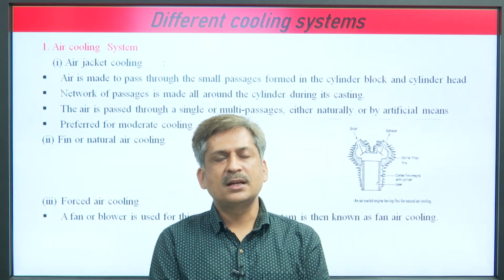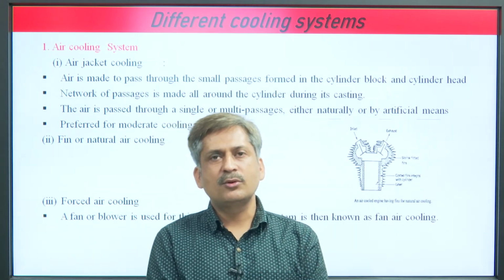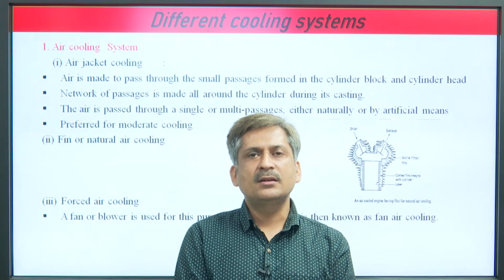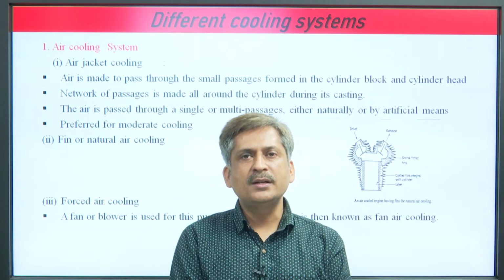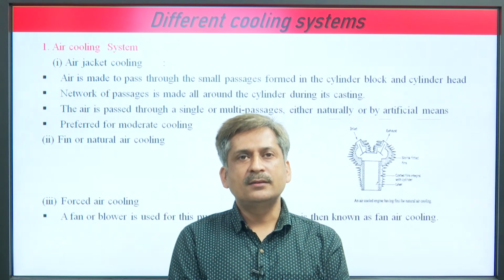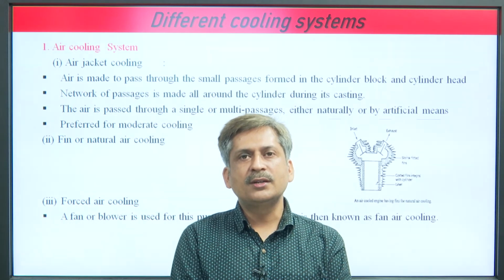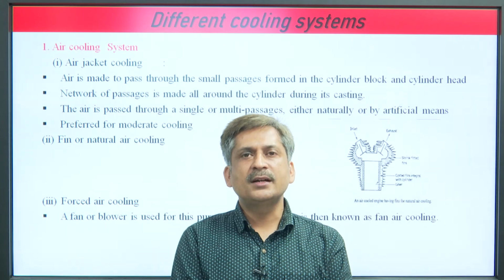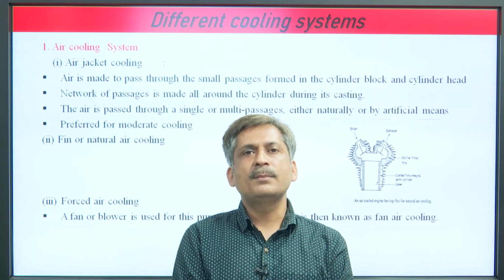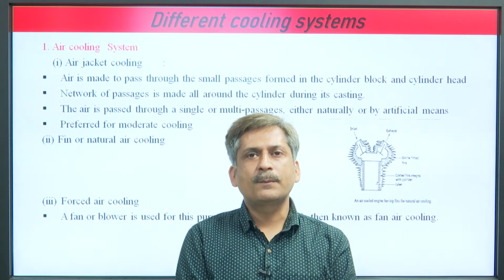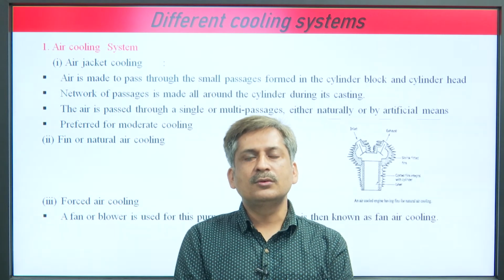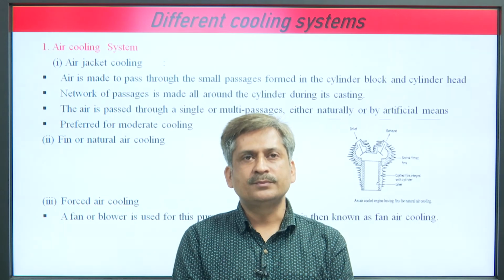I have discussed that it is required for small capacity, because in a small capacity, low CC engine, a low quantity of fuel will be burnt in a given time, and if low fuel quantity is burned, then low heat will be generated, and low heat generation results in low temperature rise. So, it can be controlled with the help of air passages or flow of air over the engine components.